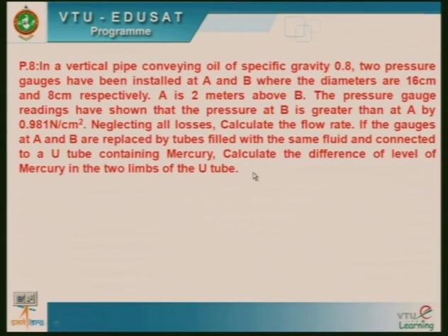This is the problem. Now, again I repeat, whenever you are solving energy problems and Venturi meter problems, you need to remember three things. One is continuity equation, Bernoulli's equation or the total energy equation, and the discharge equation for this Venturi meter. What is the discharge equation? Actual discharge is equal to coefficient of discharge into A1 A2 into root of 2gh divided by A1 square minus A2 square, whole thing under root. This is the formula you need to remember.